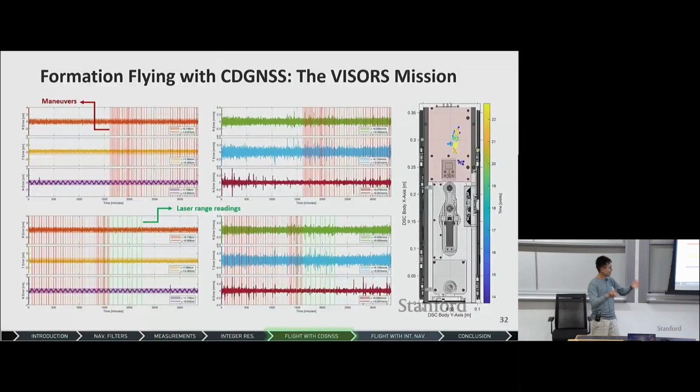Just some current measurement performances based on the current state of the software that we are in right now. This is a campaign where we do a role switch. We have one spacecraft perform maneuvers at the start. So these red translucent lines are maneuvers. And we do a role switch midway into the campaign. We have the other spacecraft. So we do a kind of a handshake, and we have the other spacecraft play the role of the maneuvering spacecraft. We check that the navigation flight software is able to receive these and include them as part of the orbit, the time update step.